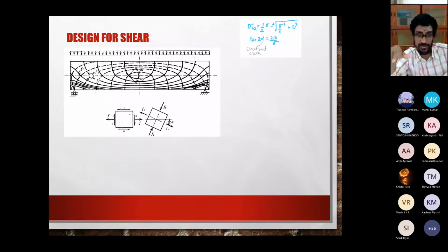It will also have shear stresses because of the shear force. If you take out a certain square element at a point, it will have a normal stress caused by the bending, and a pair of shear stresses because of the shear force.